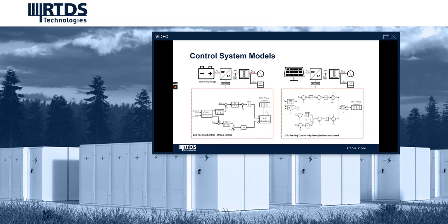There are several characteristics that determine the modeling of control system and their operation. This includes the grid strength, the kind of load, the saturation and the grid harmonics. The control system parameters have to be selected and tuned for different operation conditions such as grid connected and islanding mode, transient faults, and the addition of more renewables and distributed generation onto the grid. The RTDS library has extensive models for generating the control systems for renewable and energy storage applications.